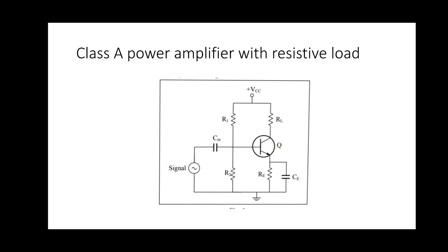The difference of power is VCC ICQ minus VCQ ICQ, equal to ICQ into (VCC minus VCQ), equal to ICQ square into (RC plus RE). This much power goes to waste in unnecessarily heating the resistors. We can attempt to reduce this wastage of power.